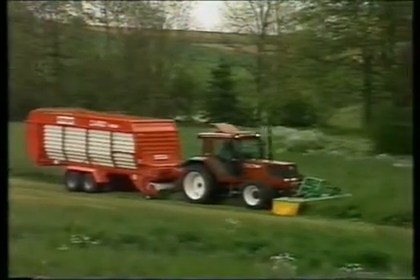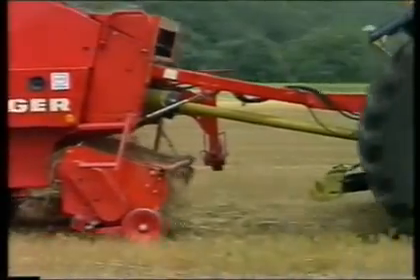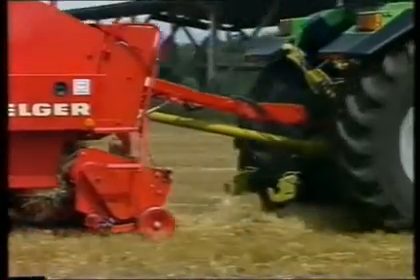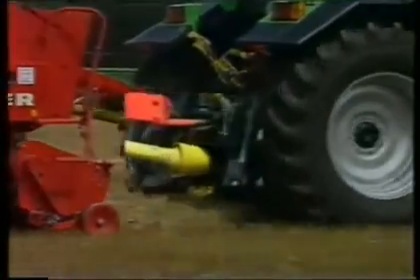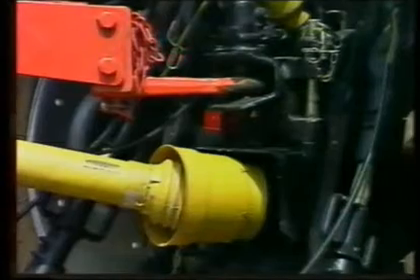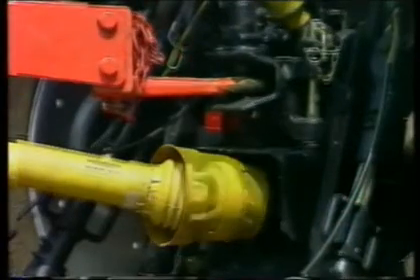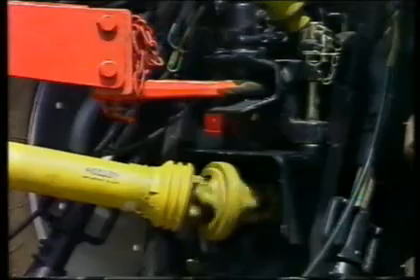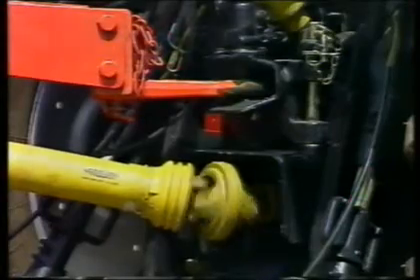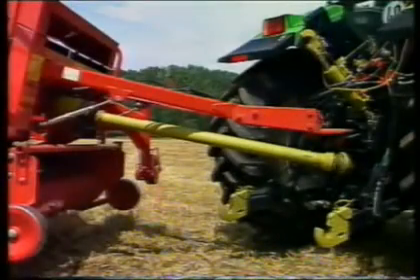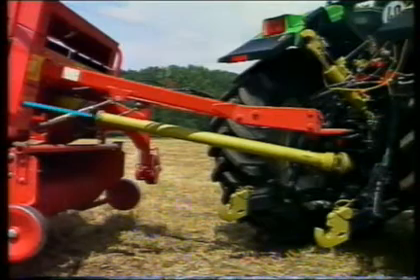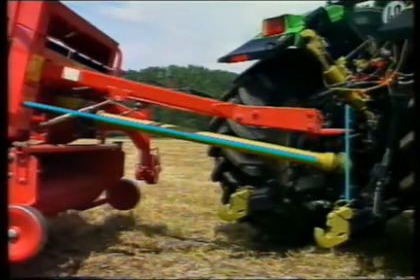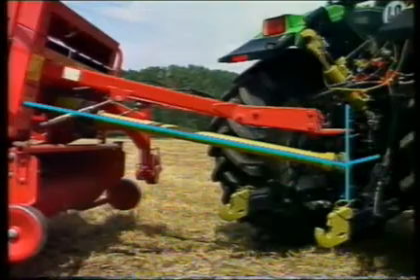A WWZ PTO drive shaft with two wide-angle constant velocity joints is necessary wherever the joints on both the tractor side and the implement side are angled and neither a Z bend nor a W bend is possible. With loading or silo trucks, the joint on the implement side is also angled, by operating the articulated drawbar for example, so that uniform rotary motion on the clamp silo is only possible with WWZ PTO drive shafts.